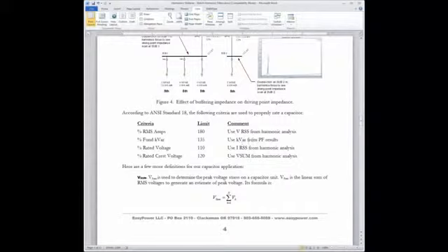What I recommend doing is that when you're in a design for a harmonic filter, that you use the V root sum square, and I'll just, in a moment, tell you the difference between RMS and root sum square off of the harmonic analysis. Use the kVAR that you see on the one line from the power flow results for fundamental kVAR.